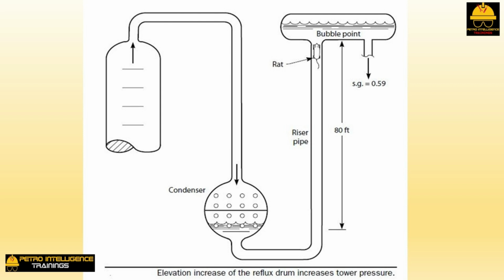Forget about the rat. I made that story up. The real story is that the riser pipe connecting the condenser outlet to the reflux drum was undersized. The project engineer specified a 4-inch pipe when an 8-inch pipe was needed. The pressure drop through the pipe was then 32 times higher than the intended delta P of 0.60 psig. Delta P in a pipe varies to the 5th power of the pipe's diameter. The resulting riser pipe pressure drop was 20 psi. This frictional loss of 20 psi in the pipe had the exact same effect on the condenser, and on the tower's pressure, as the 20-pound rat.